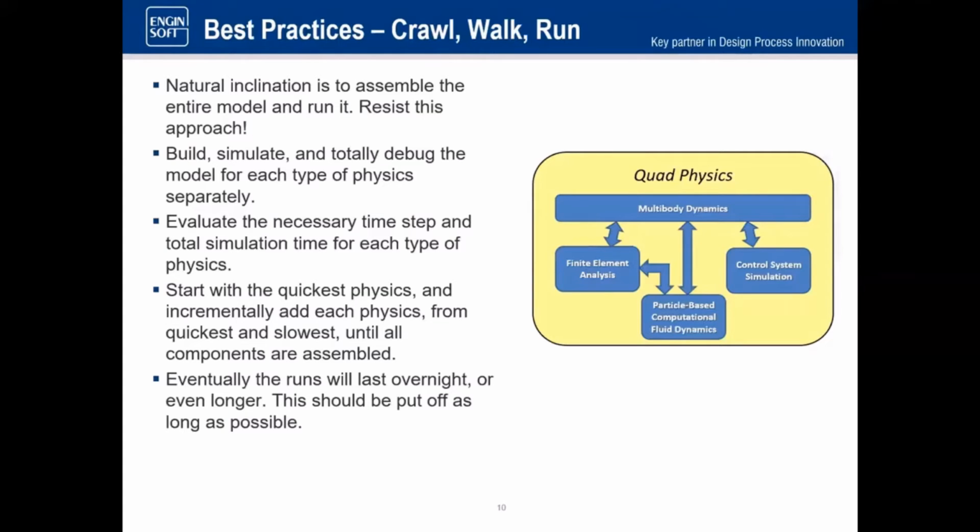So get your multibody dynamics model all assembled and tuned up. If need be, if you're going to have some flexible bodies, just put them in as rigid bodies to start and get everything else set up. And then you can add things in.